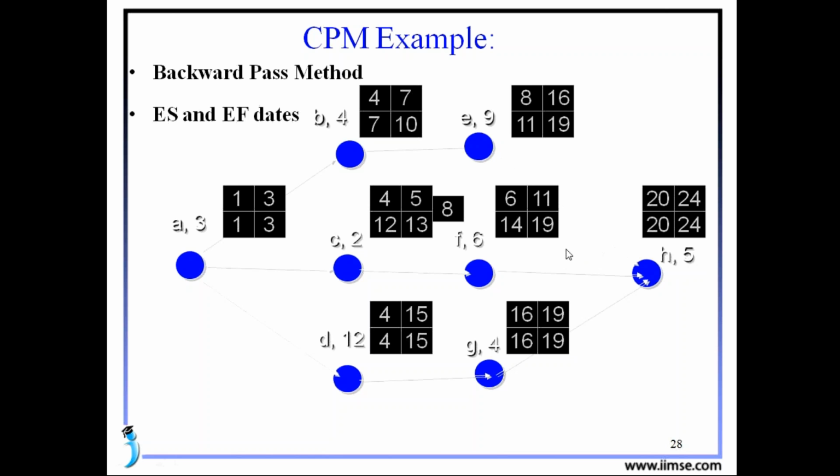If you see from the H to F, the date whenever we are starting our work of H, one day before we will get here for F, that's the 19th. And one more thing here, for the F the duration is 6. From the 19th if you remove the 6 we will get 13. Just we should add 1. Actually for that we have some theoretical calculation formulas, I'll give them later. See here, 19 minus 6 means 13, we should add 1, that will get 14. That means for the F, the late start and late finish are 14 and 19.